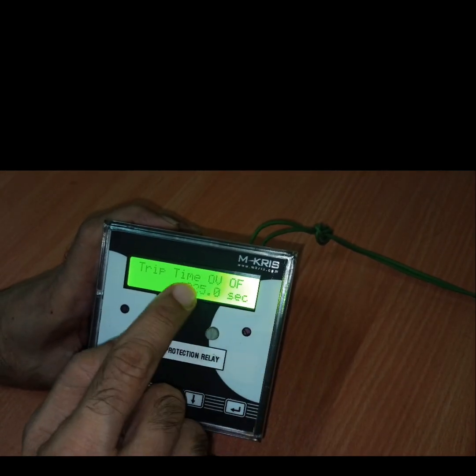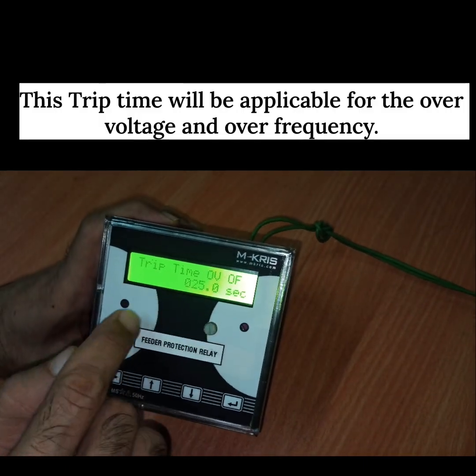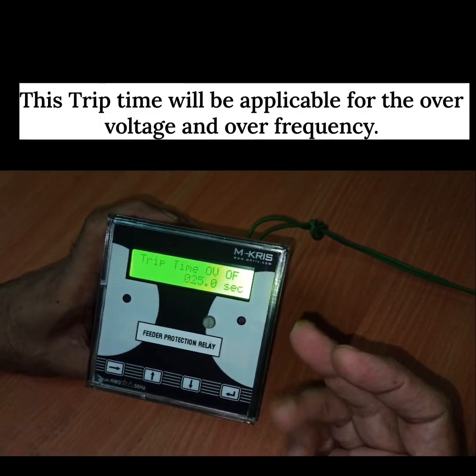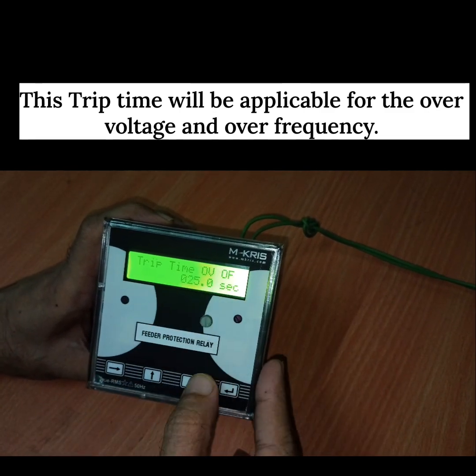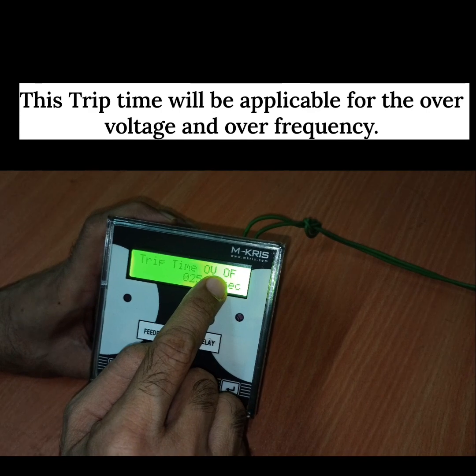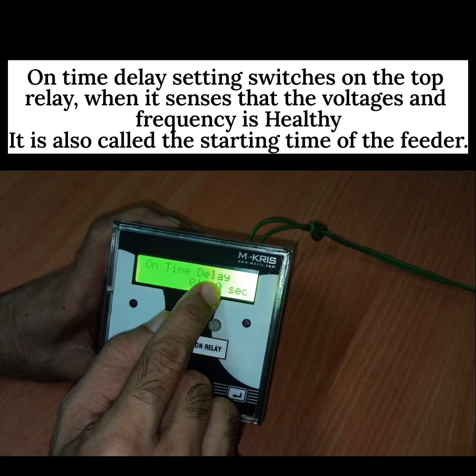This is the over voltage and over frequency trip time setting. If the fault persists for so much time, then the relay will trip. So this is 25 seconds, applicable for over voltage and over frequency. Then this is the on time delay.